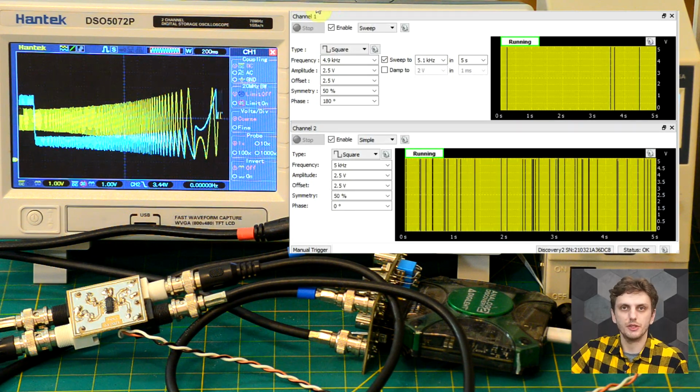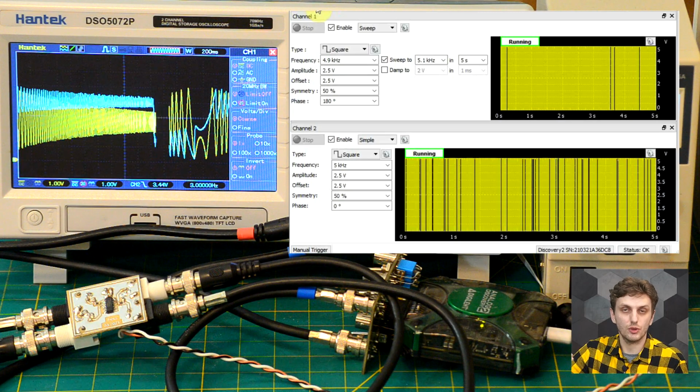So now, depending on your needs, you can use either the type 1 or the type 2 phase detector. Although the type 2 has some more interesting features, it's more complicated and this makes it work a bit slower, but it's also more susceptible to noise. So in case you get all sorts of extra transitions in there, then the output will be corrupted. The type 1, on the other hand, is much simpler, will work much faster, and you can also build it in an analog version, not just in a digital form. But that is a topic for a different time.